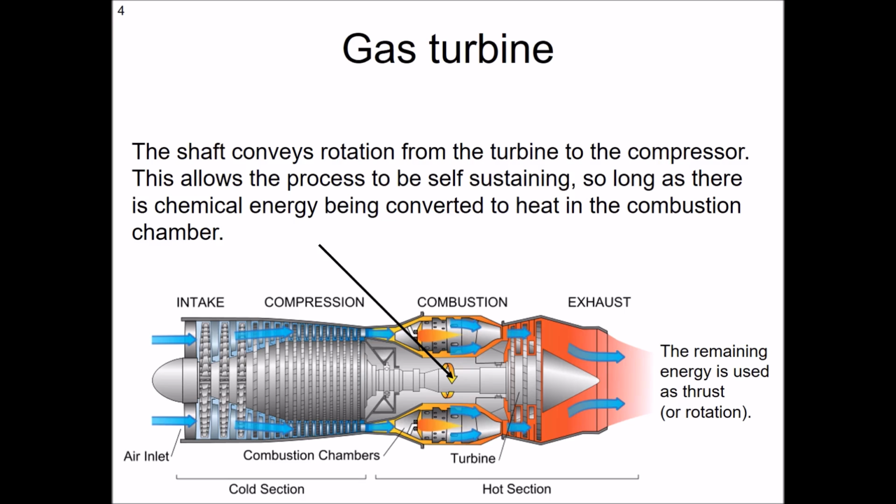So almost think about this as if it was our reciprocating engine cycle. So we've had our induction and our compression. Okay. So then we move into the combustion part. So the air is now squashed. It's very hot because it's been compressed. So if it was perfect, it would be isentropic compression. So up goes the temperature just as before.